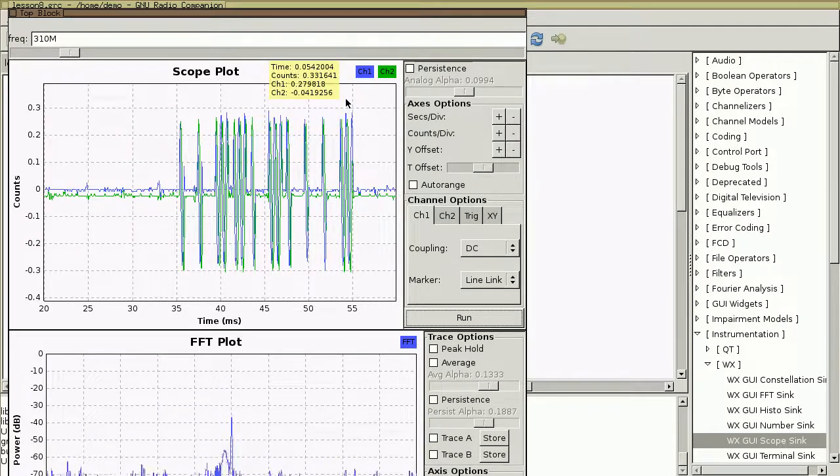And one of the things I notice about this pattern, short, short, long, long, short, long, short, short, short, long, is that it's the same pattern that I have the dip switches set to in the garage door opener remote. They're set to 0011010001. And actually there are 2 more dip switches, but we seem to be only using the first 10 here. The first 10 dip switches correspond exactly to this pattern of short and long pulses.